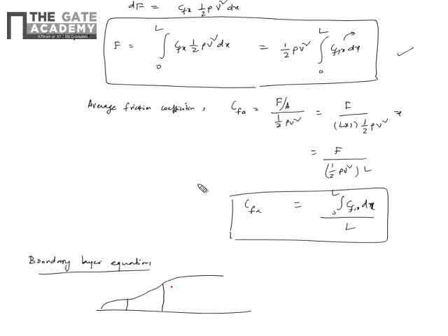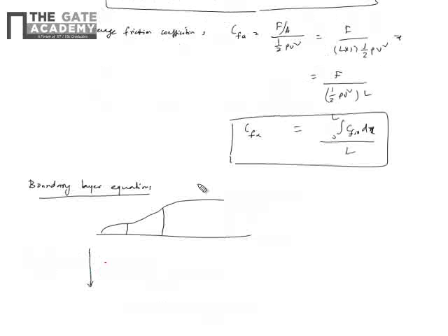But the physics is so complicated, so what is generally done is dimensional analysis. One of the most useful techniques in fluid mechanics or heat transfer is dimensional analysis, because the physics is quite complicated. The response depends on many factors, it's not simple strength of materials. So when you write down the dimensional analysis, let's say the drag force is my output. I want to know how much is the drag force on an aeroplane. So the drag force will depend on,